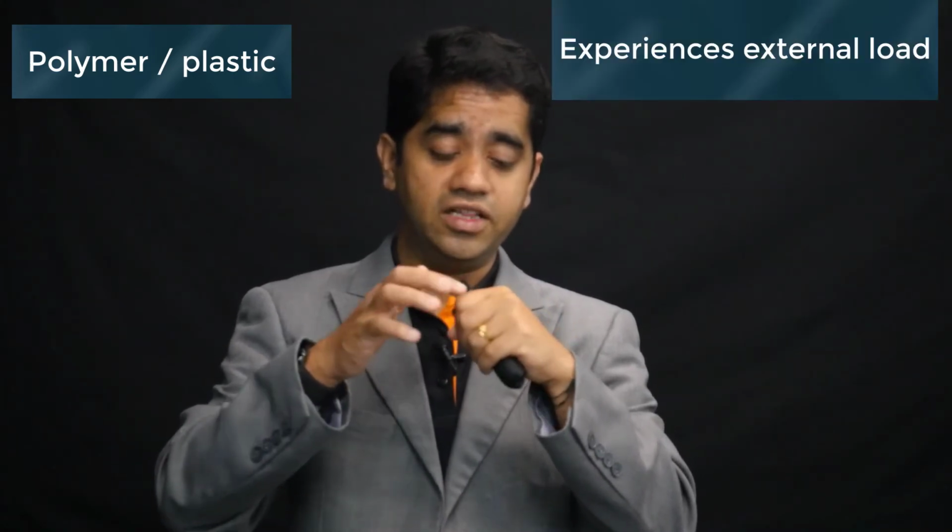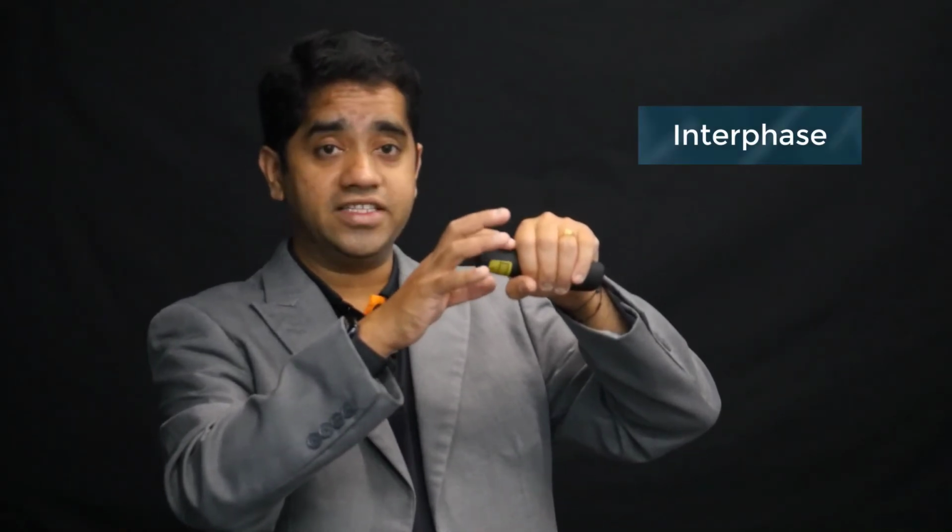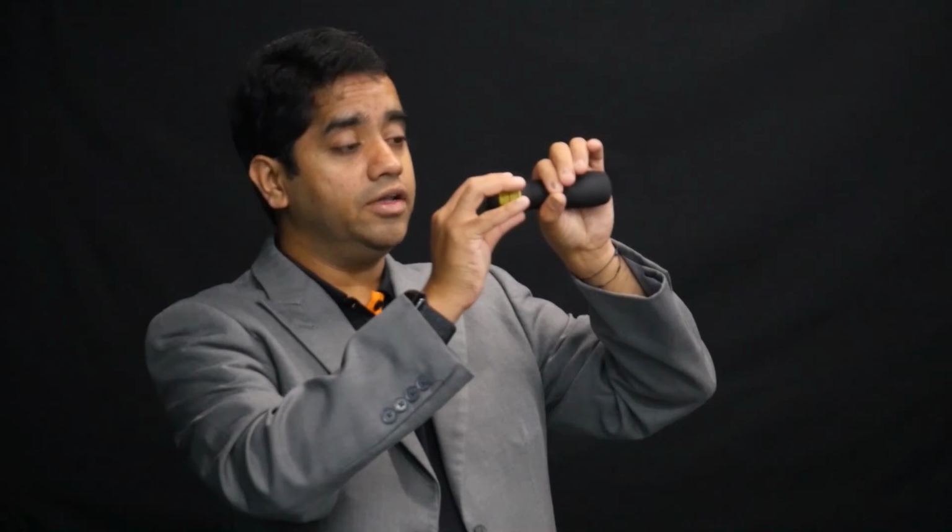And how does this whole stress transfer occur? If you consider this to be your reinforcement, and this is the polymer that is engulfing the reinforcement, and now an external stress is being applied, the polymer or the plastic, which is the dominant phase, experiences the external load first, and then it transmits the load to the reinforcements through what we call the interface. Now, if there is a gap between the reinforcement and the polymer, that means there is no good compatibility between these two. There is a gap here. Then the load transfer may not be so effective.